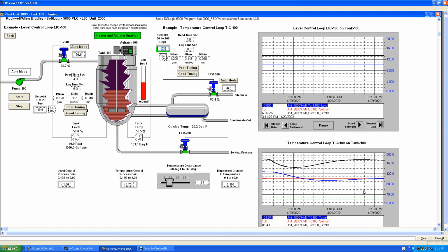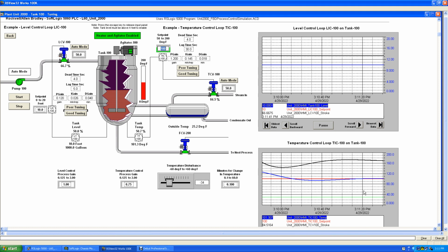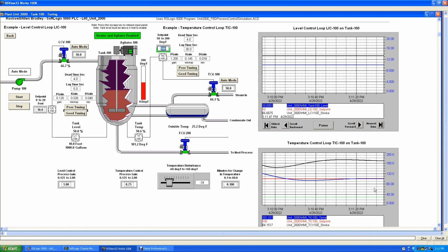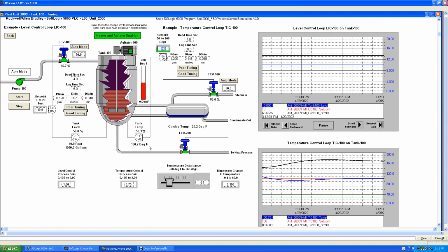And so you should have 4 oscillations before you actually come in and tune in. But they're going to be so insignificant with the overshoot that you won't even really notice it. Just the first one. And our temperature is 101.1. Now it's 100.9 and coming down. It's nearing in. It's tuning in pretty good.